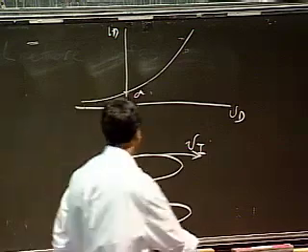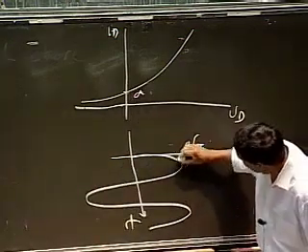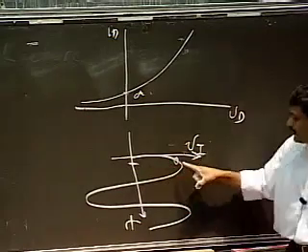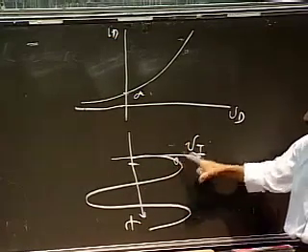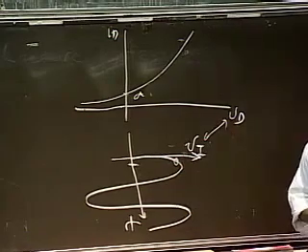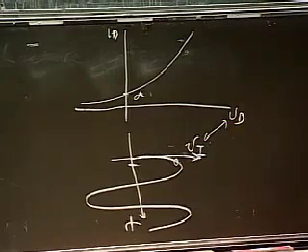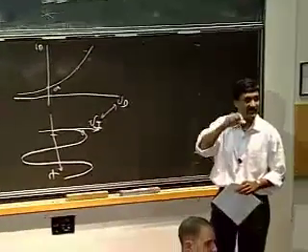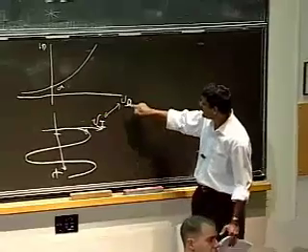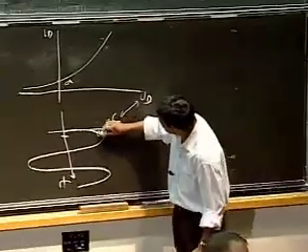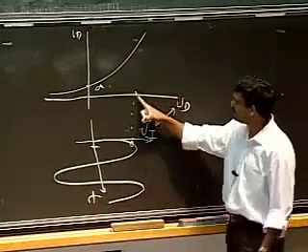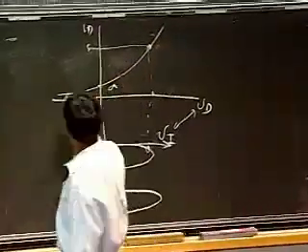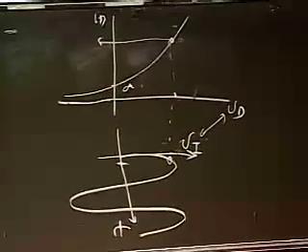So I can see where these points correspond to on that curve. Okay? So what this says is that at some point here, for example, where VI, at this point in time, when VI is here, notice VI and VD are the same thing, okay, because VI is applied across VD. Okay, VI directly applies across the device, and so VI equals VD at all time. So, this voltage here corresponds to this voltage, which corresponds to this current, and then I can find out what the current is for that voltage.